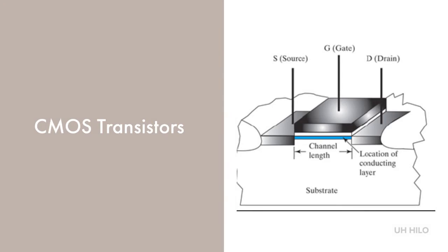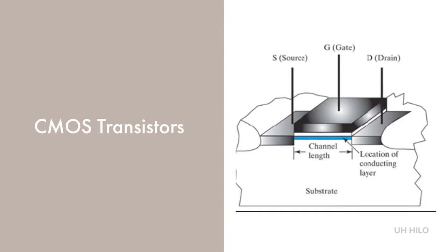In the normal operation of an N-channel MOS transistor, the drain is by definition at a higher voltage than the source. When the gate voltage is at least the threshold voltage of the transistor above the source voltage, and the drain voltage is sufficiently above the source voltage, a thin layer of the substrate just below the thin gate insulation becomes a conducting layer between the source and the drain. This permits a current to flow between the source and the drain. In this case, the transistor is said to be on.